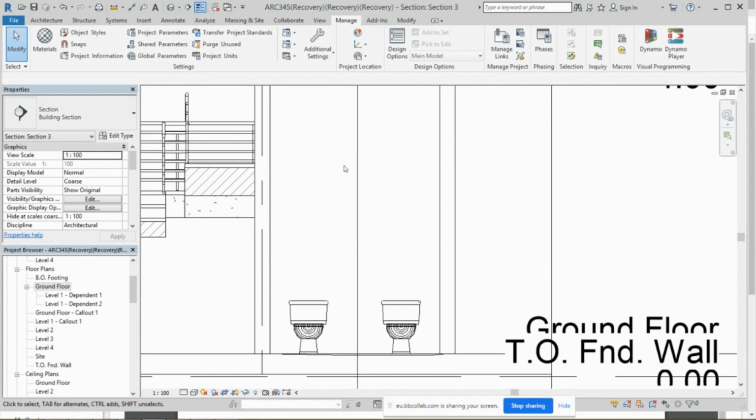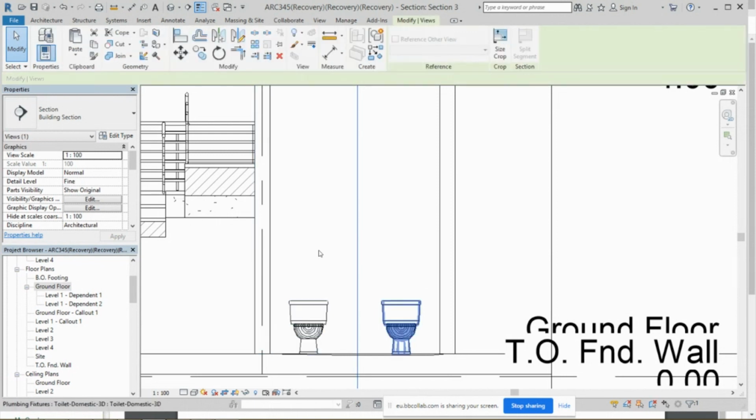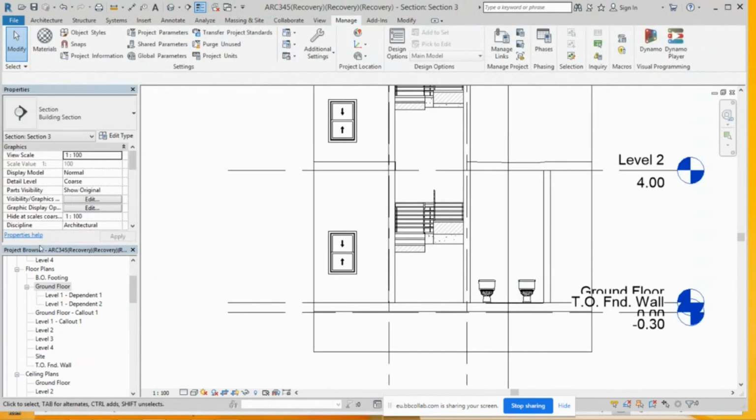If I have a light partition, it's better to treat the space as one, because the light partition is just a partition that you fix after putting your ceramic. But if you have a rigid partition formed from bricks, you do that before putting the ceramic, so you have to think of those as two different spaces. As a partition here, you treat this as one space, and you treat the other one as one space.